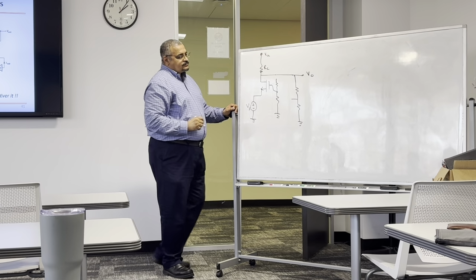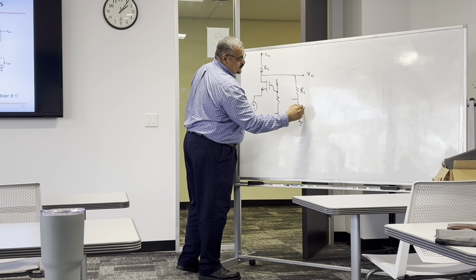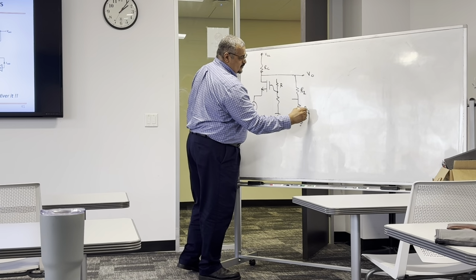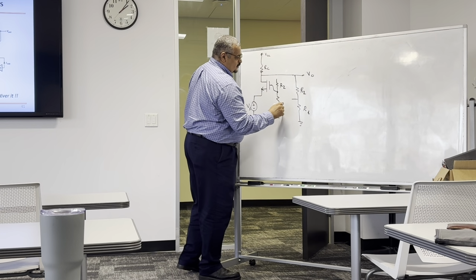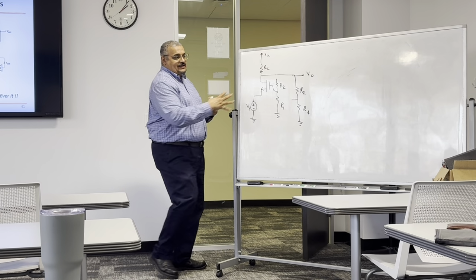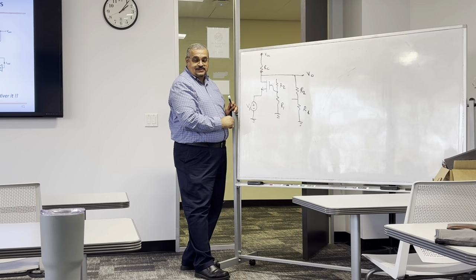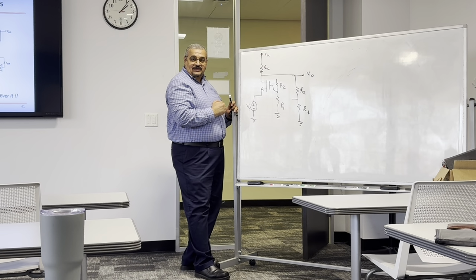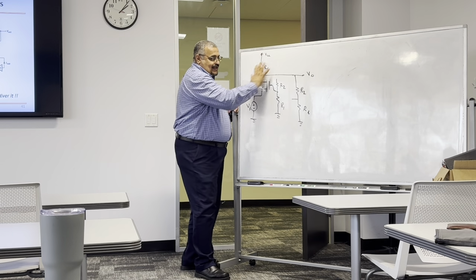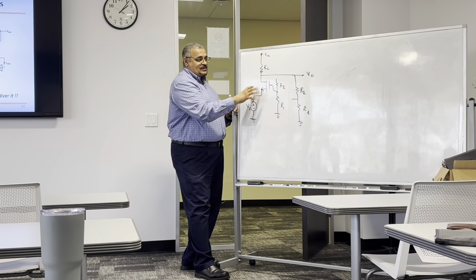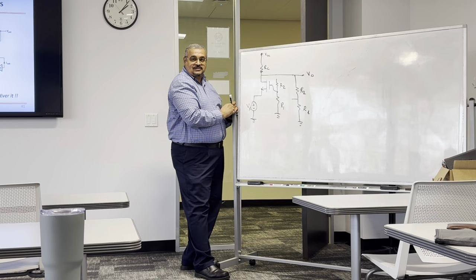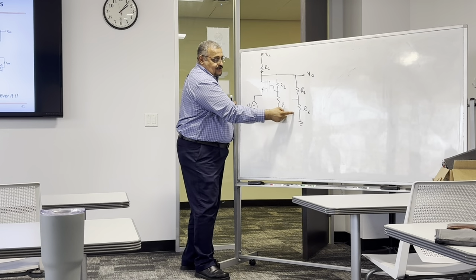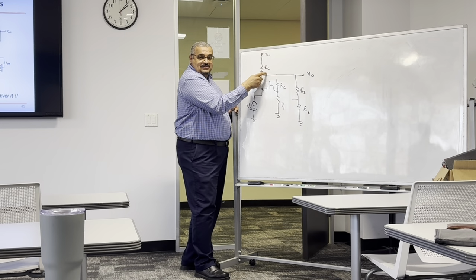Okay. So this is R1, R2, and this is, or actually this is R2, R1, whatever. So I repeated the feedback network twice. And I cut here. So this is no longer a feedback network, right? But is the gain of this one the same as the one without these two circuits? Are they the same? No, because now this R1 and R2 are in parallel with this.